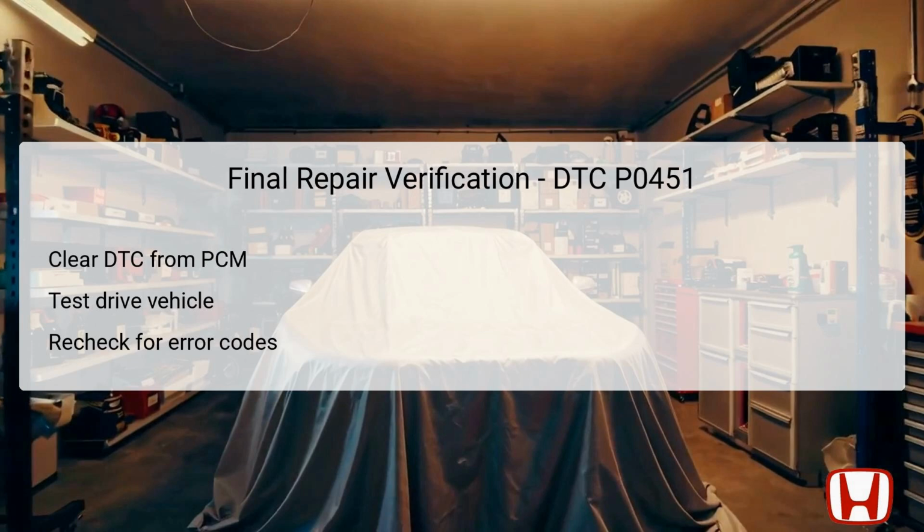Throughout this driving session, the technician should remain vigilant for the MIL's illumination or any new fault codes, ensuring that the prior malfunction does not recur. Ideally, if the vehicle operates without any disturbances and subsequent checks do not reveal a reactivation of DTC P0451, it indicates successful repairs. If any faults resurface, further diagnostics will be necessary.